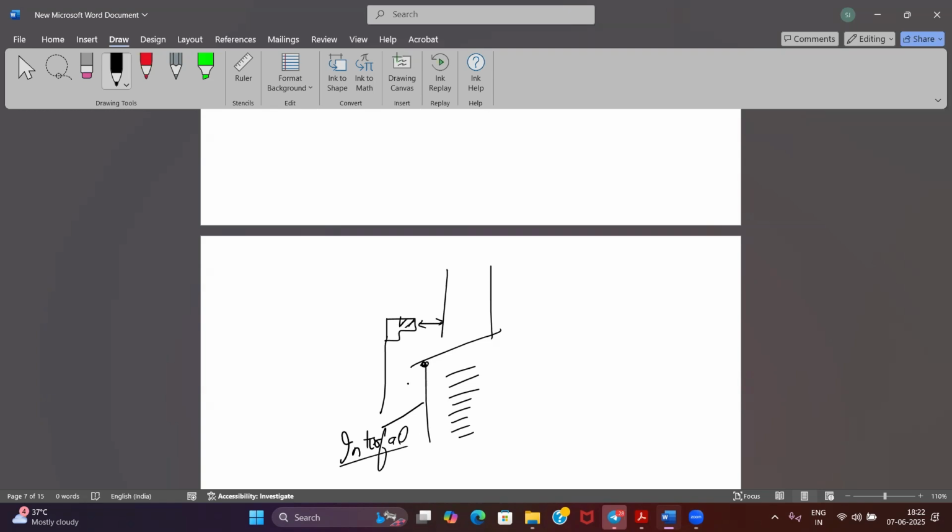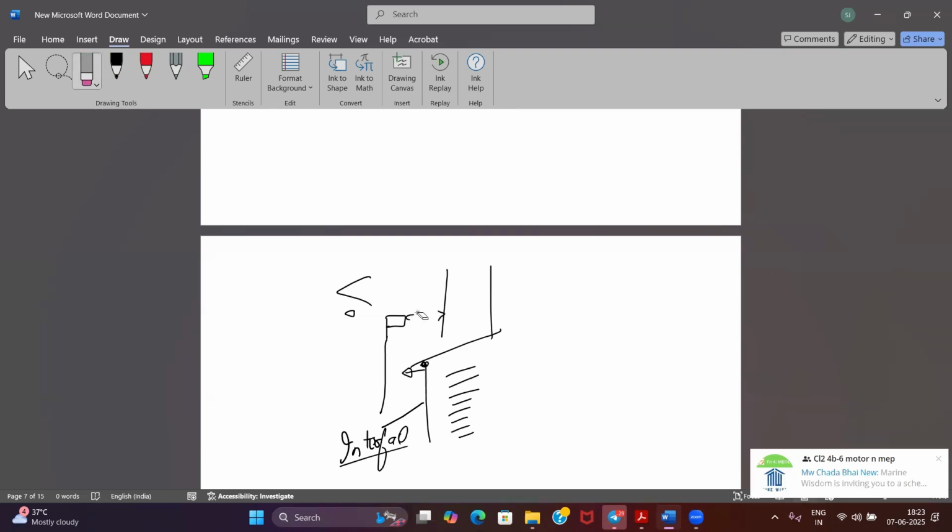So this area is right now less. Less amount of water can go out at this moment. But if I use a large gravity disk, that means the diameter increases. Now I have much more diameter, so more water can flow out. If water is flowing out, what will happen to this interface? It will shift outward, no? Yes, sir. Consider it like a back pressure valve. If I do not let water go, my interface will shift inward. If I let water go too much, the interface will shift outward. Agreed?